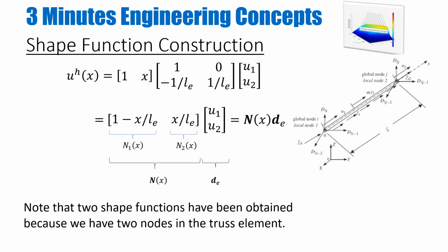We have also discussed a very important ingredient of FEM, which is known as the shape functions. Shape functions are interpolation functions, as we discussed a couple of videos before, and they describe the displacement through an element. If we know the displacement at the nodes, we can interpolate the displacement inside an element, in simple terms.